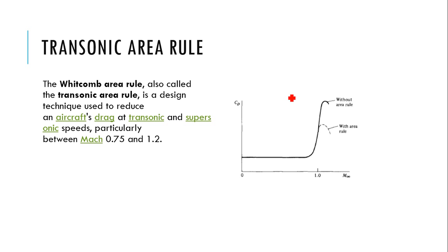So if you are using the area rule, which was prescribed by Whitcomb, we will be getting less drag, and without the area rule the drag is more for supersonic aircraft. We can see here, in olden days the aircraft shape will be like this. Here we have the wing like this, the cross section of the airfoil shape will be like this. But afterwards, because of this shape, we are getting more drag, because of the drag divergence Mach number.